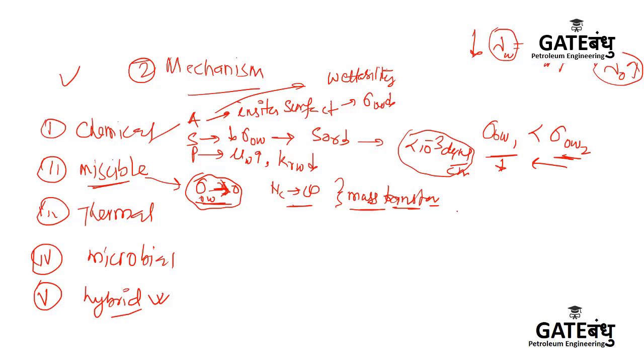These chemicals, these agents, actually try to reduce the surface tension to such an extent that there is no attachment between the rock layer and the oil, and the oil mobilizes as freely as possible. Here, for EOR purposes, you get the highest recovery factor and the lowest SOR value.